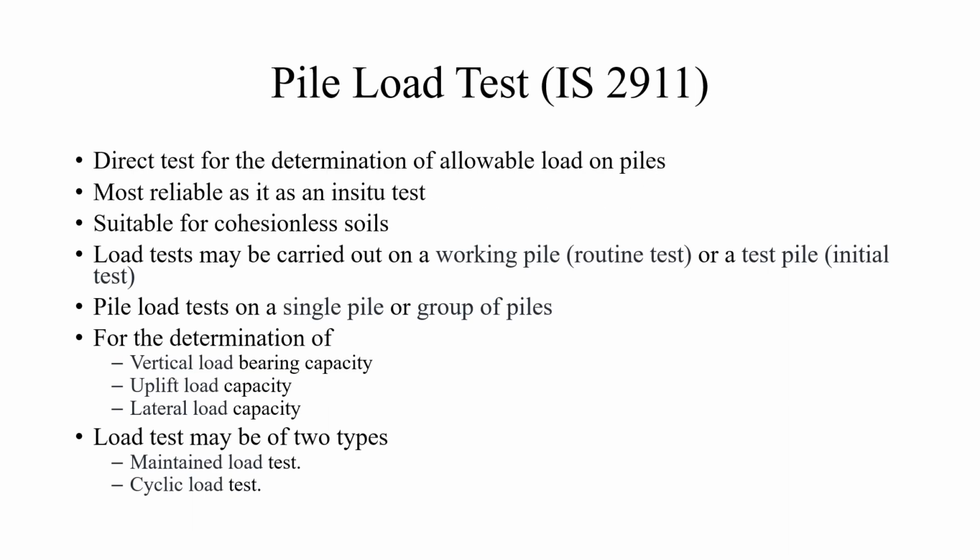Now, a pile is under the ground. We cannot go and do the test in each layer. Even while we are constructing a pile, it's a bit difficult to see how properly it has been constructed. We cannot excavate the entire depth and see whether it was properly excavated or properly compacted, etc. So what we do is, after constructing a pile, we do the pile load test. The pile load test is done on the field and hence it is one of the most reliable tests that has been done. Now we learn about pile load test.